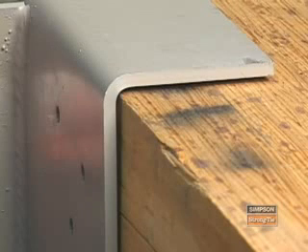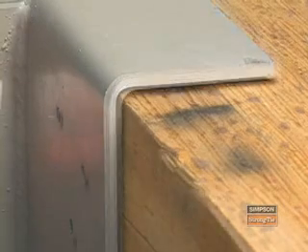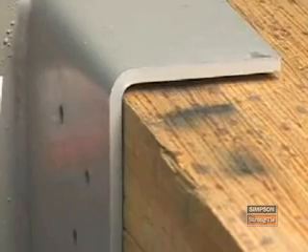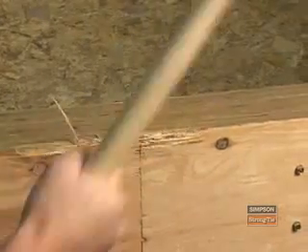Because of the thickness of the steel, top flanges of a heavy-gauge top flange hanger are curved at the bend and do not have a perfect square corner. The curvature of the top flanges makes it difficult to get the hanger flush against both the top and the face of the header. Therefore, you might have to round off the corner of the supporting member.